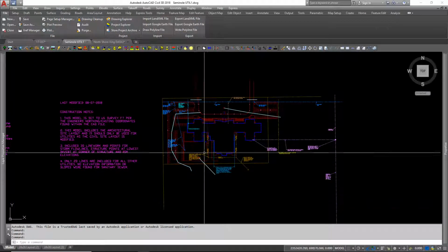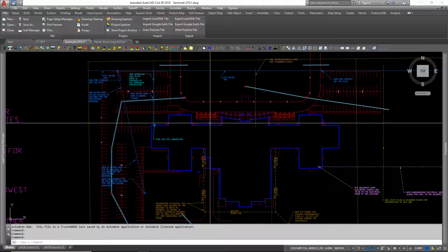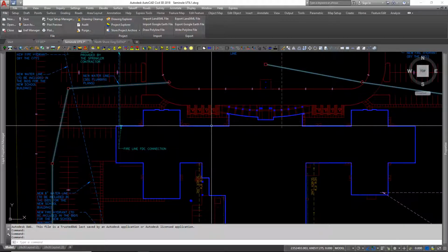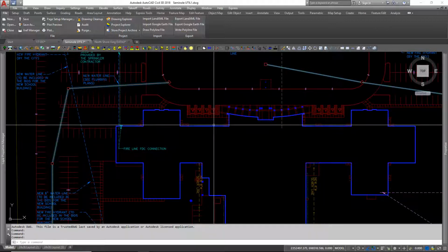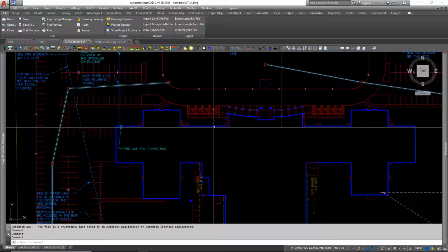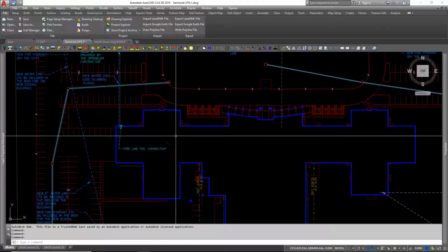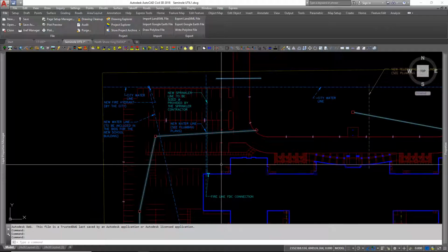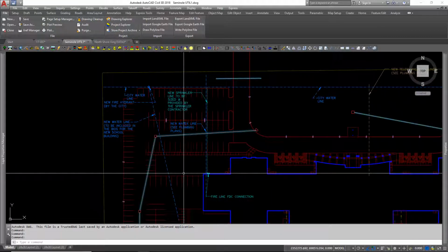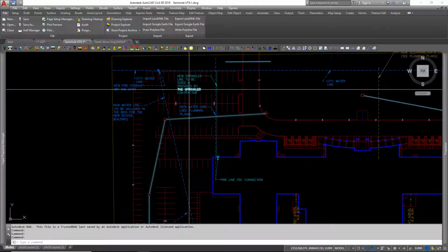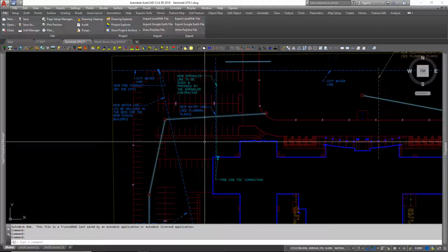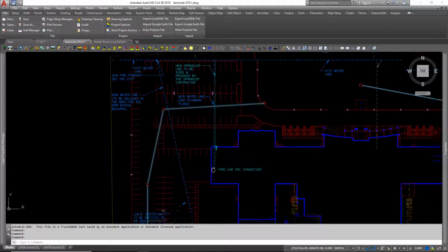Here's another real decent idea with just a simple storm layout. So a lot of times what happens is they may start the grading and not be sure about the utilities, they're still getting worked out, or the job is just so detailed that we'll provide a 2D file for layout. This one happens to be for water layout, so you can see that we've given them a lot of text, which back in the old days with smaller computers and processors on field computers were a problem, but now it's not so much of an issue.